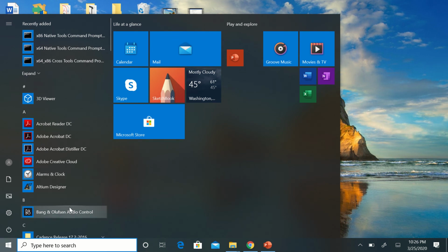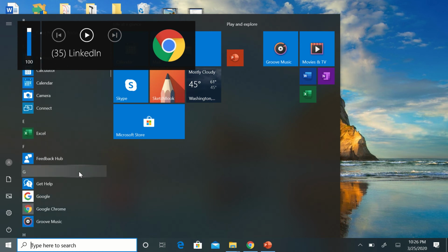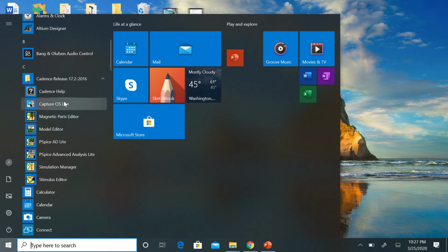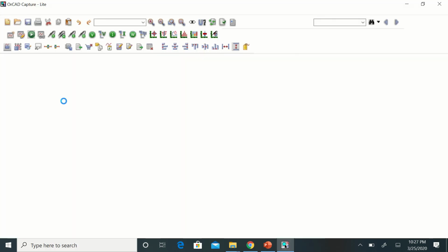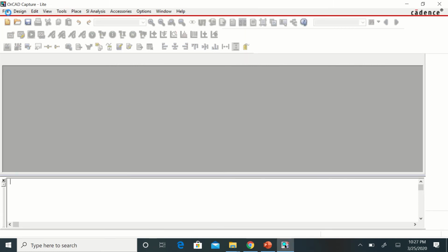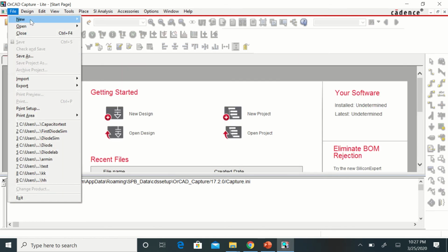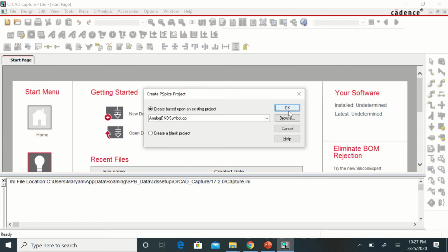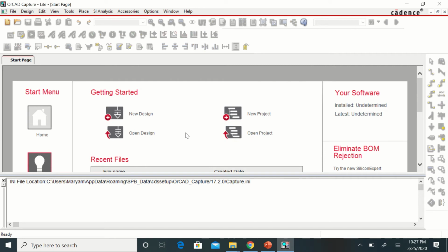Hello, so this video is about the RC circuit that we already talked about. So I want you to go to Cadence Capture, and we are going to open a new project. File, New Project. Let's call it RC circuit. Press OK. Create based upon an existing project, so we'll have our ground available.